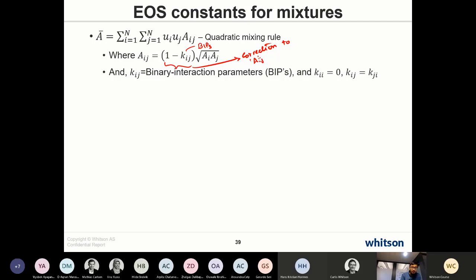And yeah, so again, Curtis can tell you the stories about why the correction term is introduced as 1 minus Kij rather than just a correction term. We saw that we have a correction term to the small a in terms of alpha, and then we have a reduced temperature, for example, in the Redlich-Kwong equation of state, and that this is just a correction term alpha, but the correction term here is not just the Kij, but it's 1 minus Kij. And Curtis can tell you the stories. Curtis, do you want to comment on it?